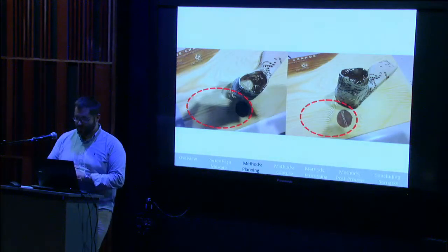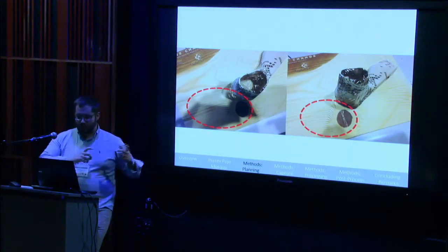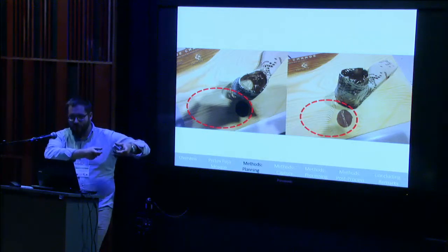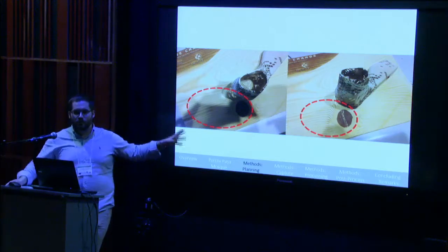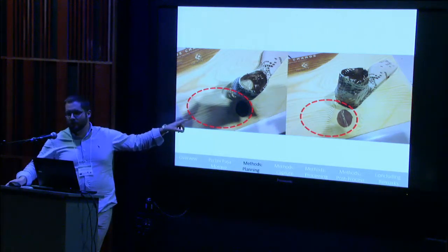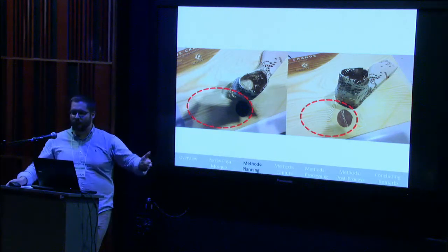The other one is shadows. So here I intentionally leaned over, got in the way of a light. You create the shadow that creates an artificial point that the software might try and latch on to, saying, oh, this is a point, let's look for it in other pictures. Can't find it, so it gives up.